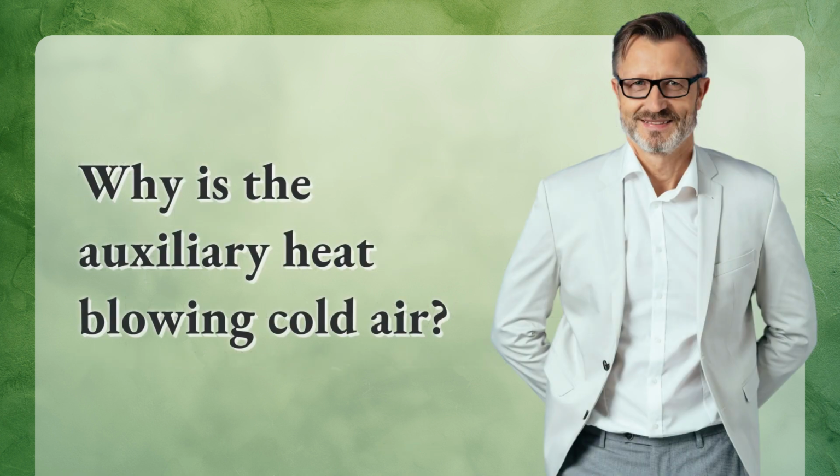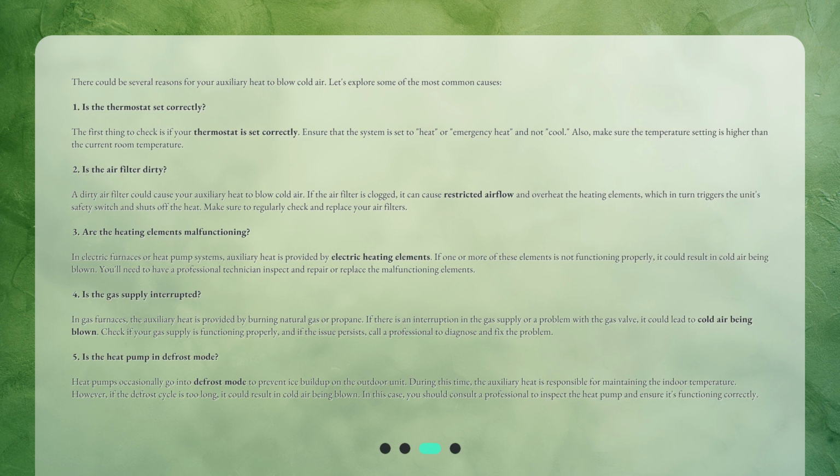Why is the auxiliary heat blowing cold air? There could be several reasons for your auxiliary heat to blow cold air. Let's explore some of the most common causes. 1. Is the thermostat set correctly? The first thing to check is if your thermostat is set correctly. Ensure that the system is set to heat or emergency heat and not cool. Also, make sure the temperature setting is higher than the current room temperature.